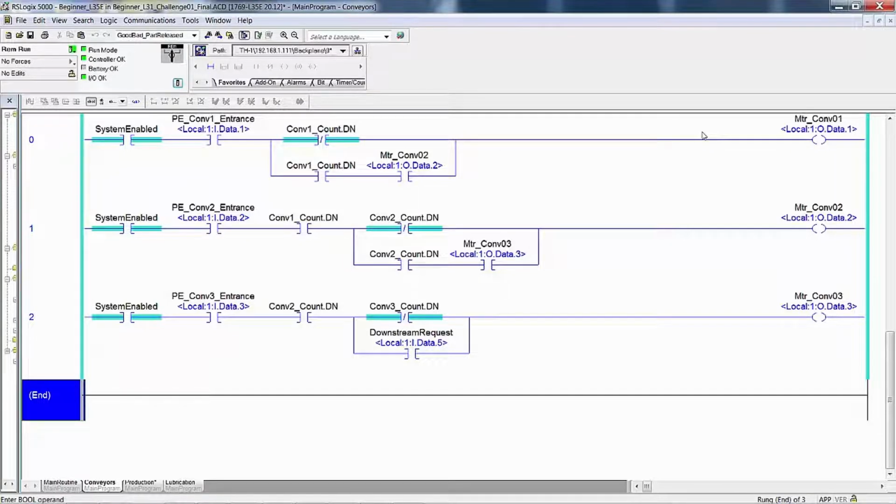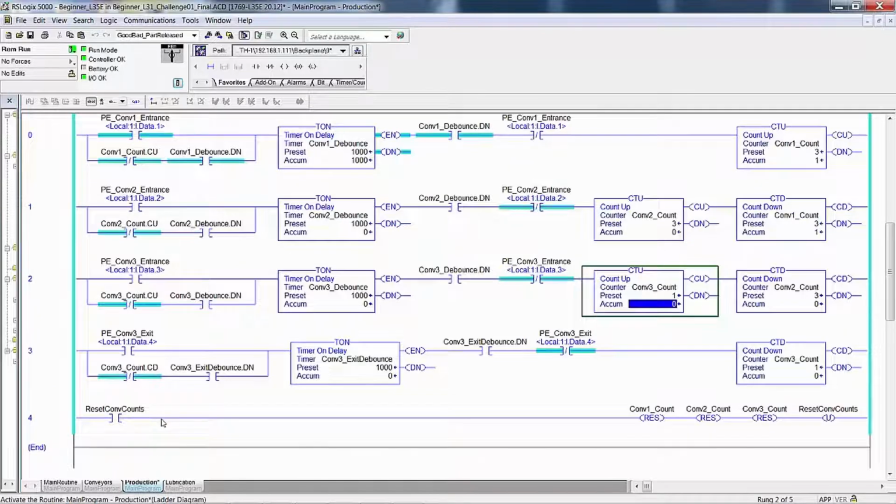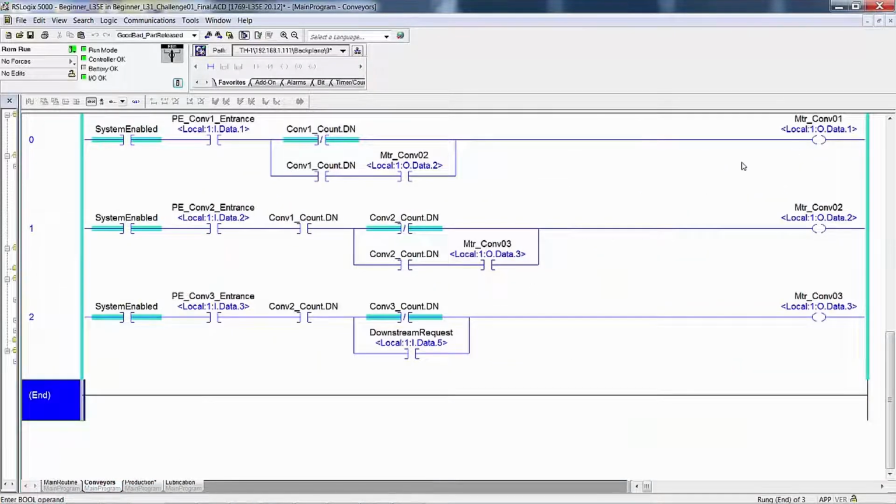So we're looking at the conveyors now, so we switch PE on again. Conveyors are running. We go over to production and we turn off the photo eye. See, we count up to 2. Go back to conveyors and the conveyor's not running. Did any conveyors run? Yes. Which? Conveyor 1. Did conveyor 1 counter increment to 2 when PE went to the off state? Yes, it did.